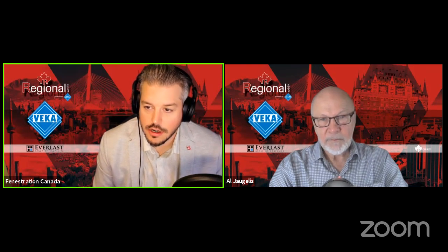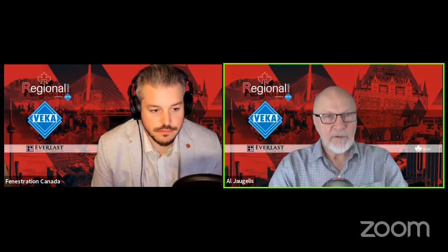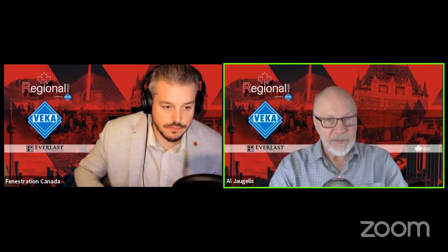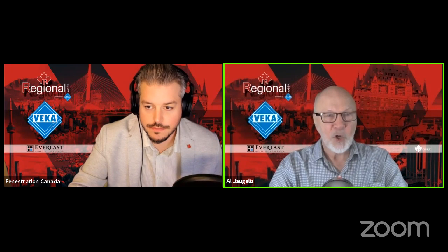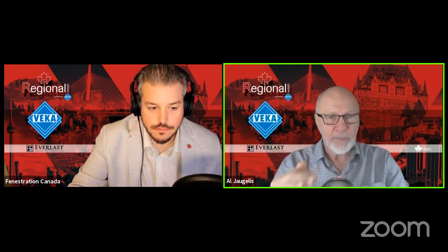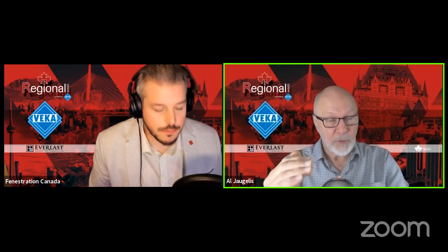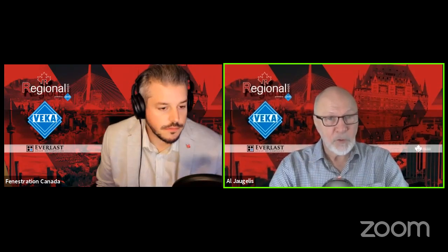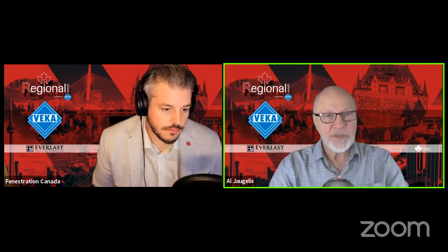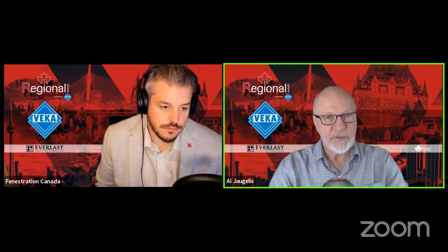Okay. Can you please shed some light on whether fire-rated doors are covered or not in NAFS? My vendor says fire ratings trump NAFS. Your vendor is correct. Fire-rated doors are not in the scope of NAFS. Remember we talked about the scope of NAFS, and I said one of the products that is excluded from the scope is those commercial steel doors. They are outside of the scope of the standard. They're not intended to be tested to that standard.